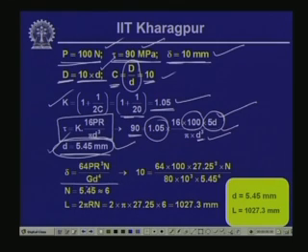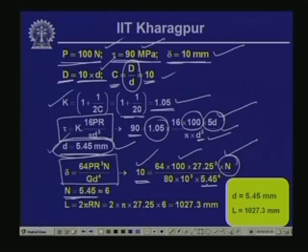Now, from the expression of the deflection, delta equals 16 PR cube n by G d to the power 4. If we limit the deflection to 10 millimeter, and since all other parameters are known except the number of turns n, we can compute the value of n, and n comes out as 5.45 from this expression for the diameter of the wire as 5.45 millimeter.